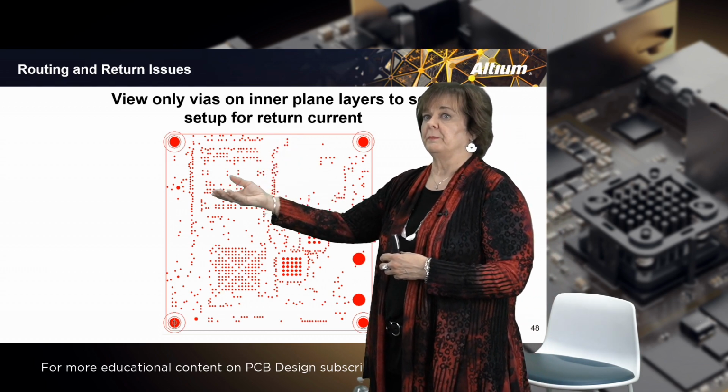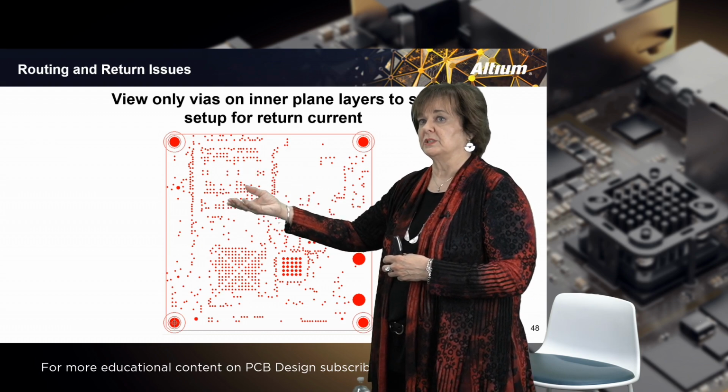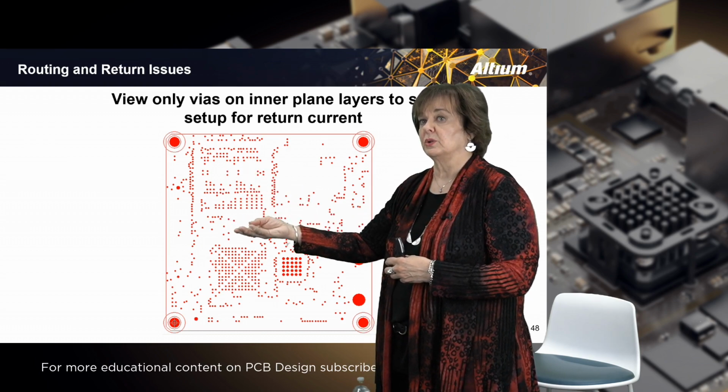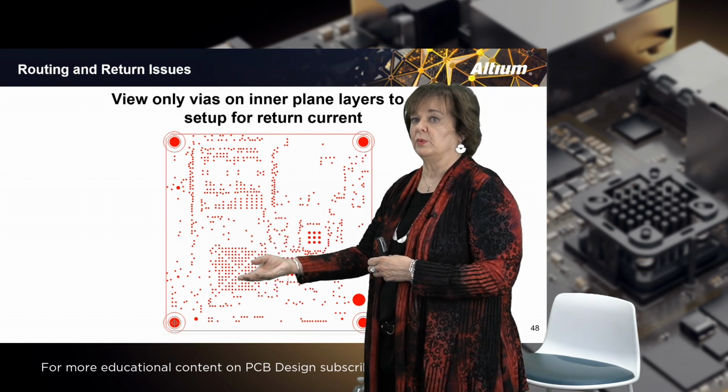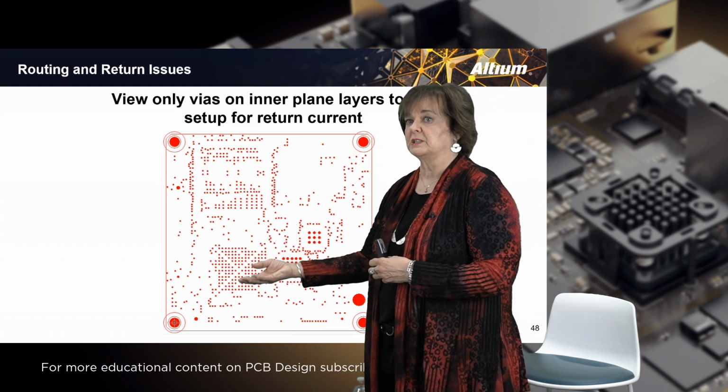Here you've set them up into a good pattern to allow those signals to go north-south and allow the return path to go north-south. Here's a good indication of what you can do with a BGA just by the X pattern that you can see.